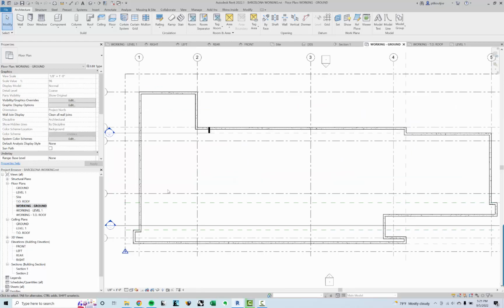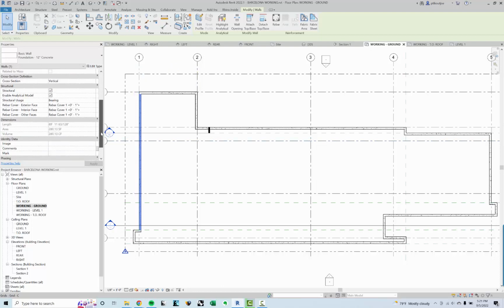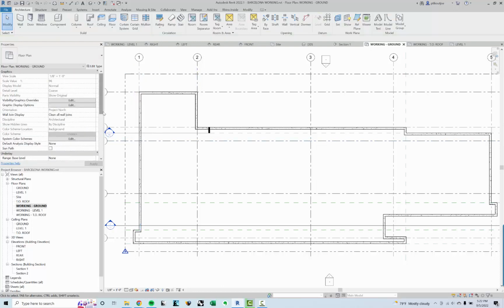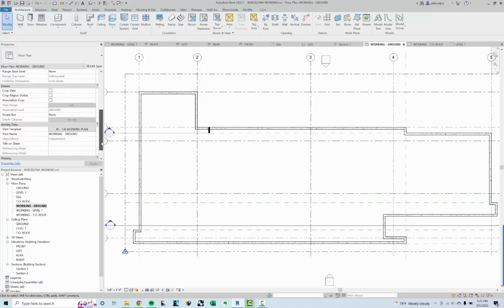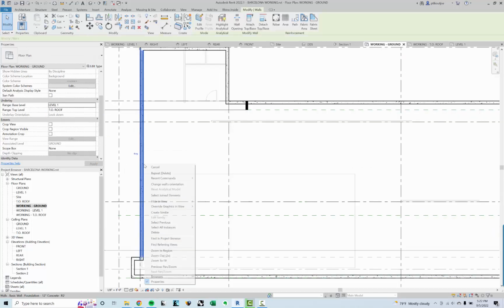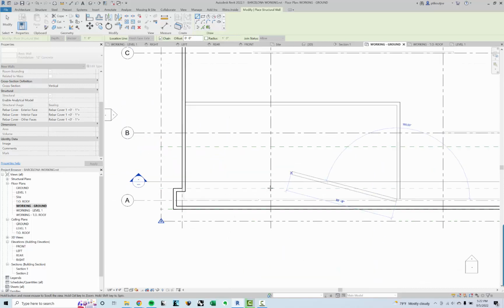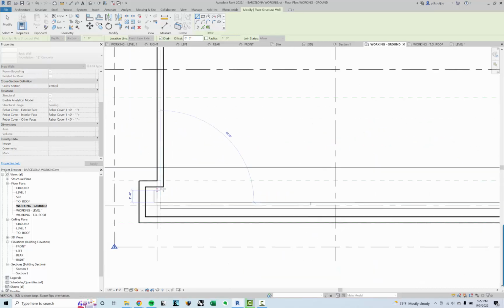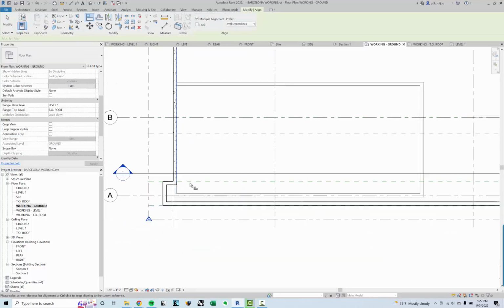So the last thing we'll do before we wrap this up is I'm going to add a foundation around those so I can see, we get that clean look in there for the pool. So let's put an underlay first floor. So now I can see my pools. I'm going to create a similar one of these. I'm going to flip it. Okay.